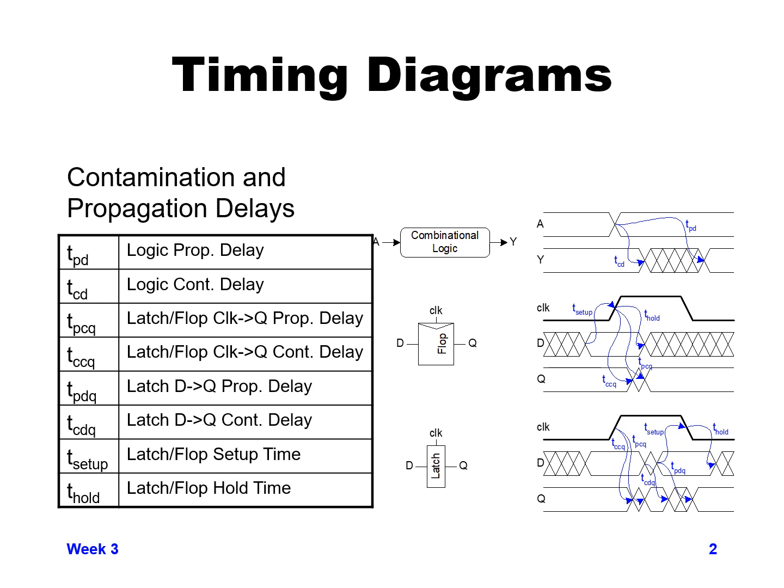If you've done that, then when your clock rises, you will get an output, and that output Q will be a sampling of D. One timing will be your flop propagation delay, which is the longest amount of time it takes after your clock rises till you get an output, and one will be the contamination delay, the shortest amount of time it can take to get it out.